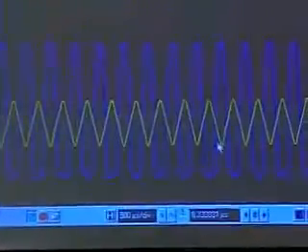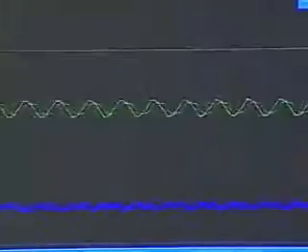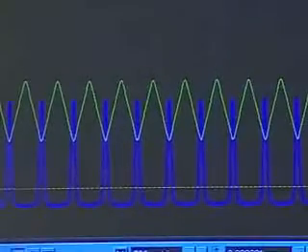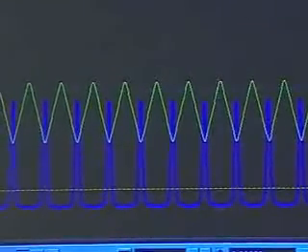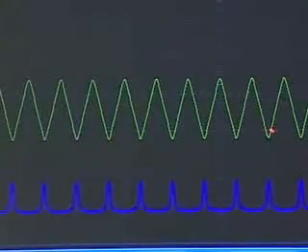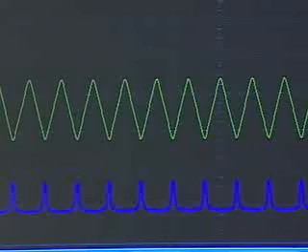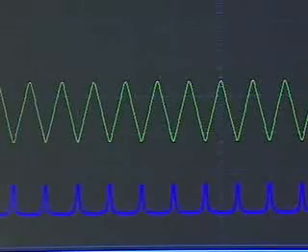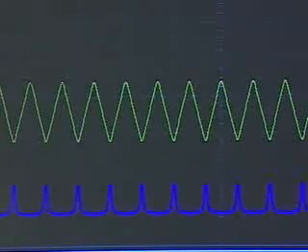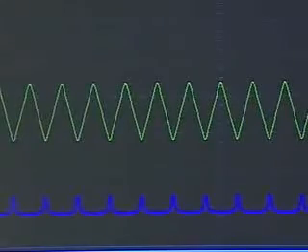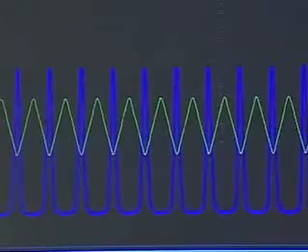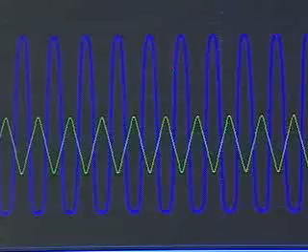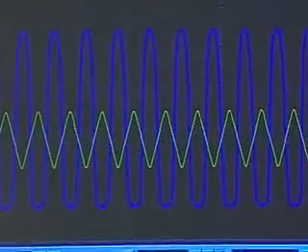So you'll notice the input going higher and higher. I'm going to pull the trigger point down. There you go. So notice that as I boost up my input even higher, notice that the output is a really small image of what the right output should be. Okay, the right answer here, of course, is that I apply some right amount of offset to boost up the input into the right regime so that the output is seen to be some amplified version of this input.